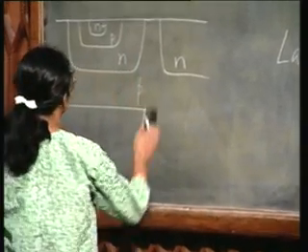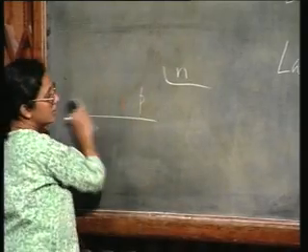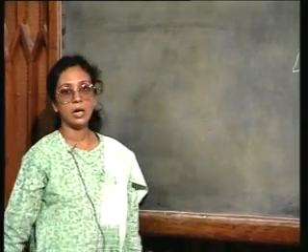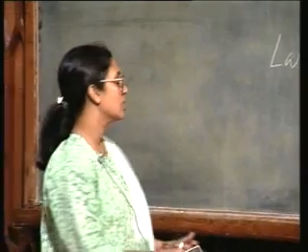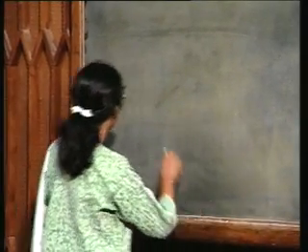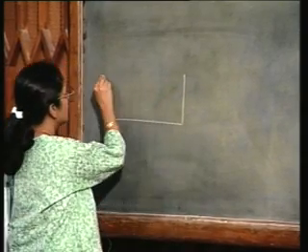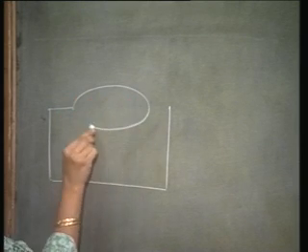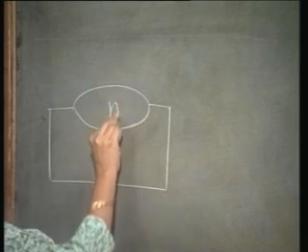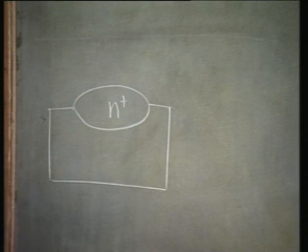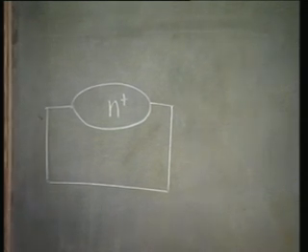The other technique that was used, again in junction isolation, was called collector diffusion isolation, CDI. In this, what you do is, you start off as before with the p-type substrate, and then you have the N plus buried layer. Up to this, it is identical to the older bipolar junction transistor technology. The difference is after this.